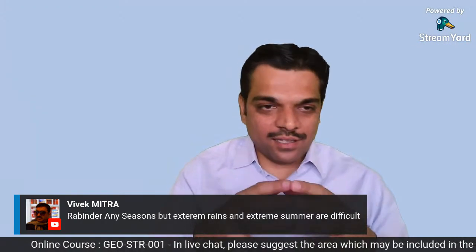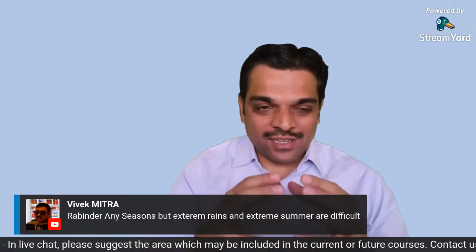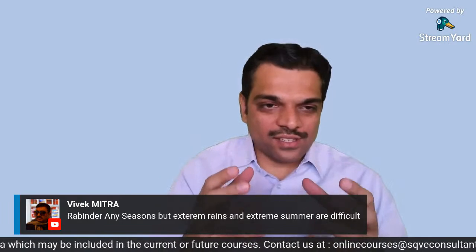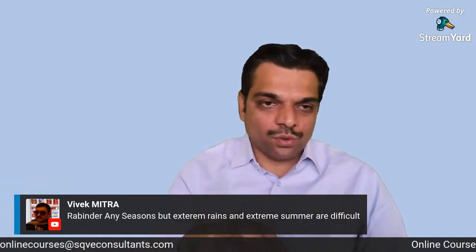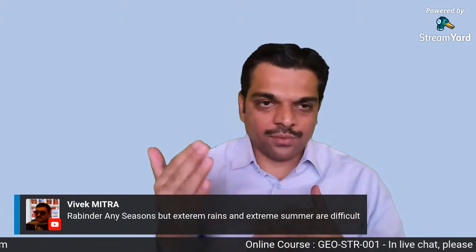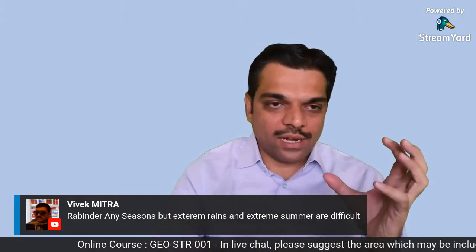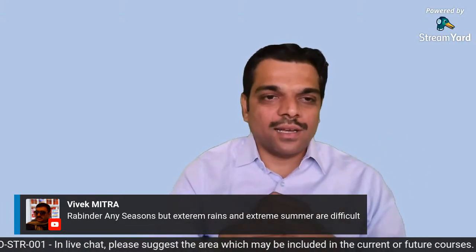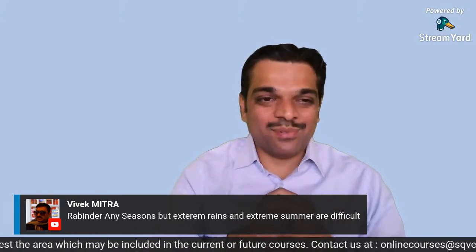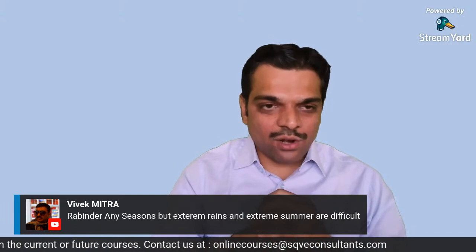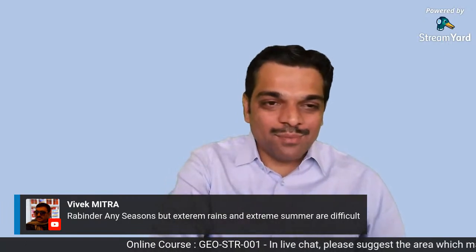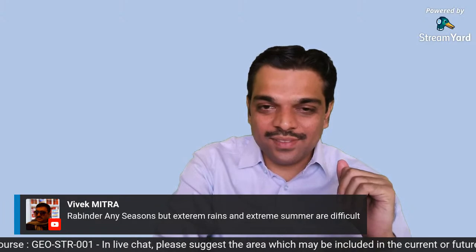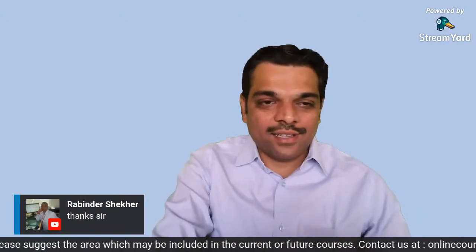Generally, in my opinion, the bulb which is considered for the design, I think hardly it is getting formed on the site, and sometimes the underream piles are used extensively for the whole tension force. See, let's say my foundation is in axial tension, so the whole tension is being transferred through that bulb, single bulb or a double bulb. Personally speaking, I am not in favor of underream piles, because there are a lot of problems with respect to the bulb formation, and the entire tension load capacity transfer mechanism is dependent on that bulb. Okay, but it's a very good question which we have received. Okay, yeah, Ravinder Shekhar is saying thank you, so most welcome.